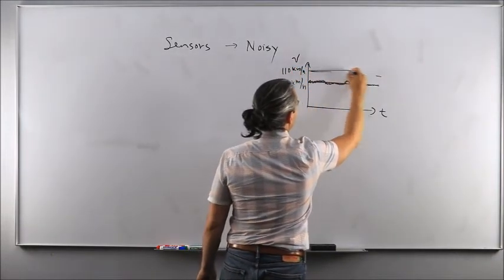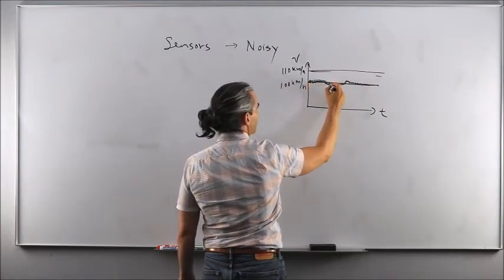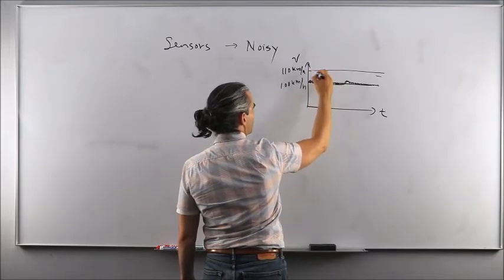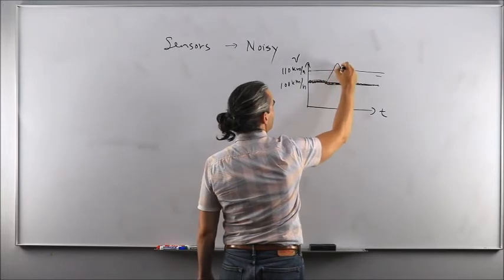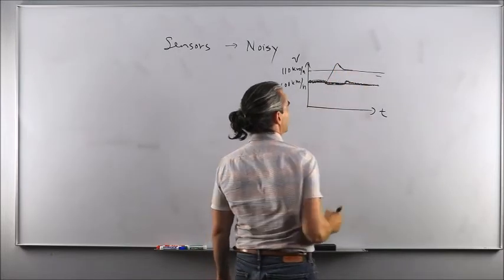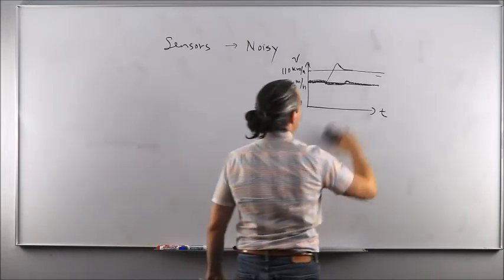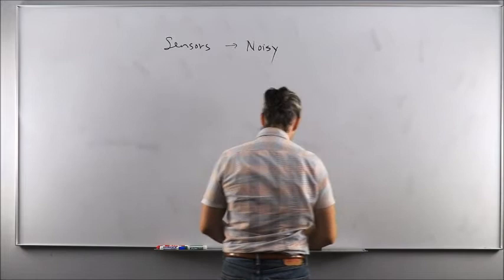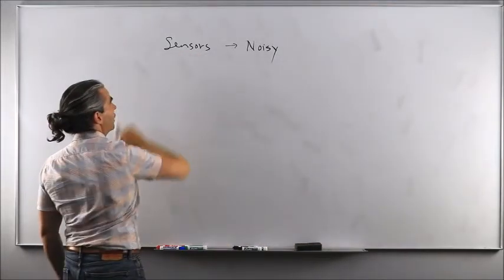Okay? So here, because the controller thinks you are slower, it's going to provide a larger acceleration than was actually needed, and then the actual speed will maybe go above a little bit or overshoot the command, things like that. So noise is an inherent part of any control system, because control systems rely on sensors.